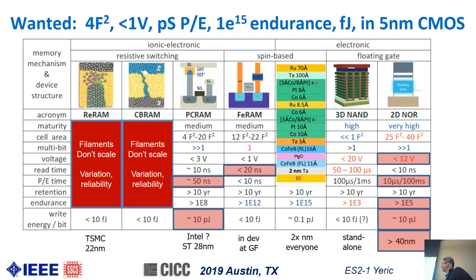You can buy MRAM. So you put all these angstrom level platinum, cobalt, iron, everything that's going to take a fab down from an impurity standpoint, stick it in a resistor, and you get a resistance difference of 2 between on and off, right? So again, as designers, it's not the best technology in the world. It's just what we have available. It is fast, so it's got a potential speed-wise, and it's got pretty good endurance. So there's hope for MRAM. You just have to be able to design with this factor of 2 difference.